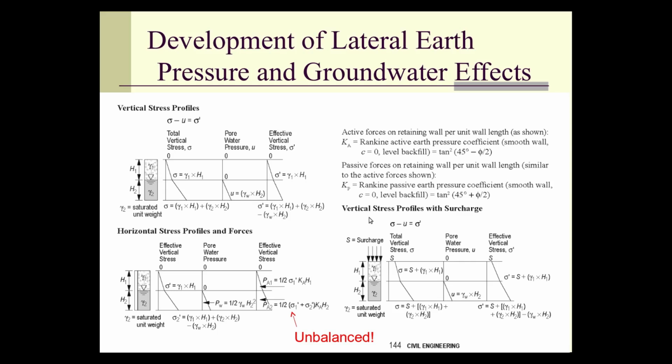This is from your FE exam. I would strongly suggest that you study this carefully. This is a nice presentation of it. For the FE exam, generally speaking, the lateral forces are restricted to Rankine with obviously delta equal to 0, no cohesion, and level backfill. And those are the formulas which we have for those. And we've seen those before.